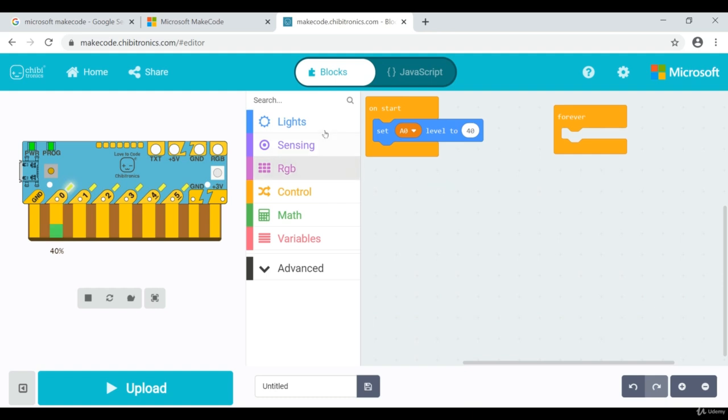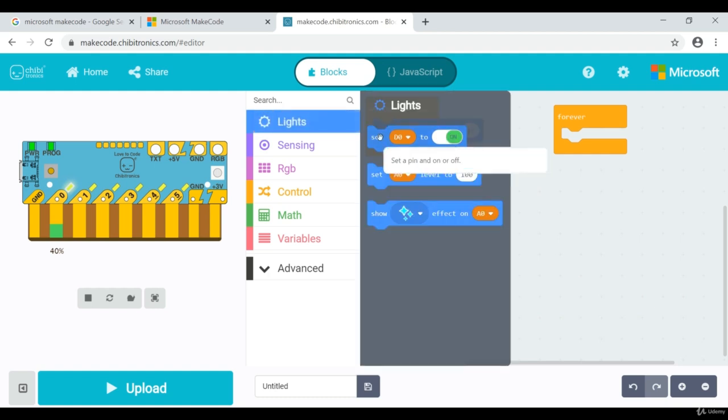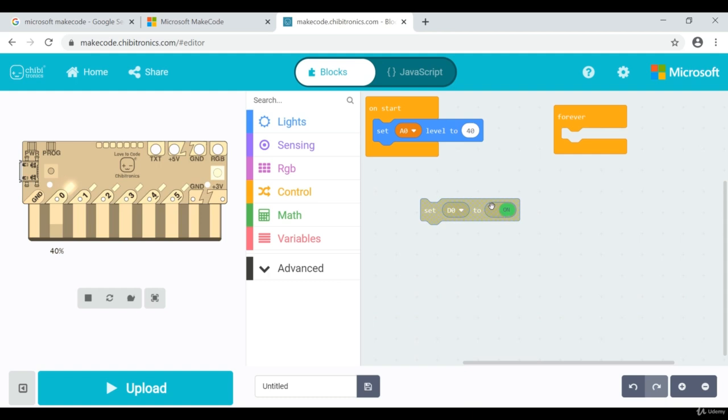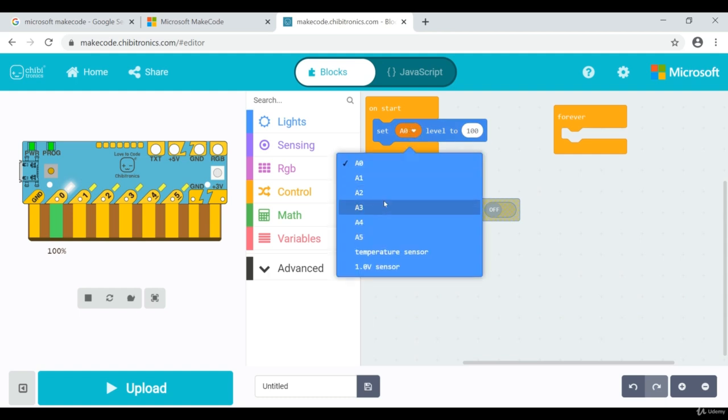The earlier function that we were using was digital function. There were only two options. Either you can put something on or you can put something off. But here we can change the level. So this is known as analog control, where you have the option of changing the intensity or capacity of any output device to the required capacity you want. This was a very basic example of what can be done with this chip. So let's move on to the next exercises.